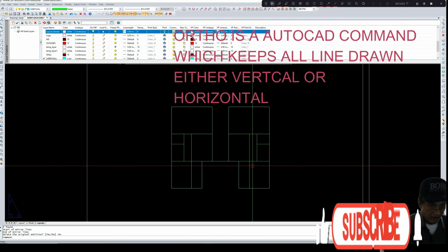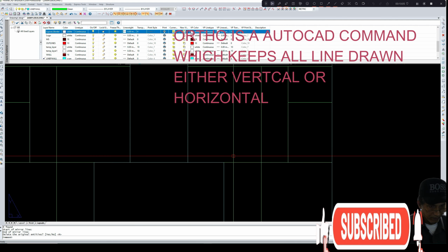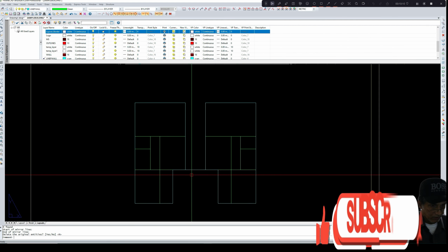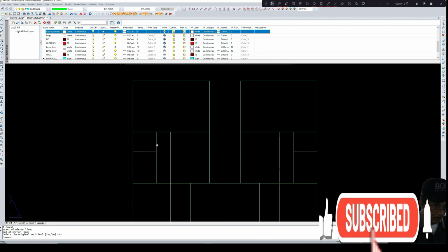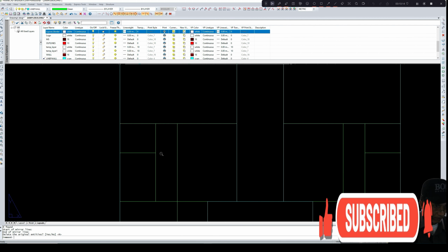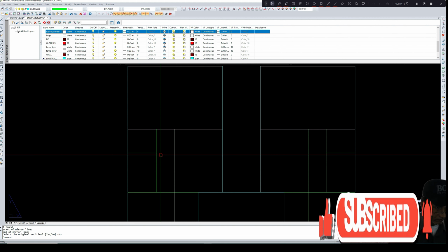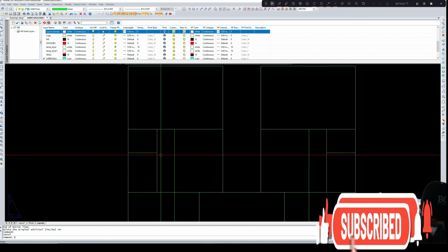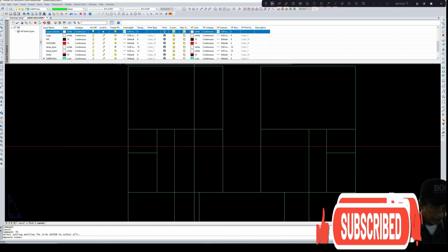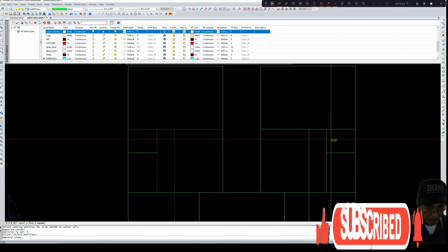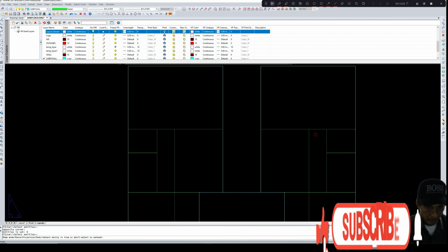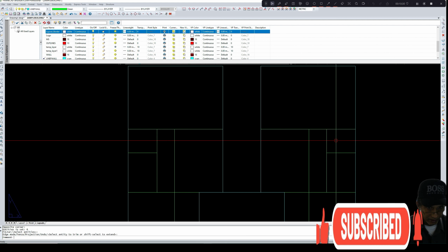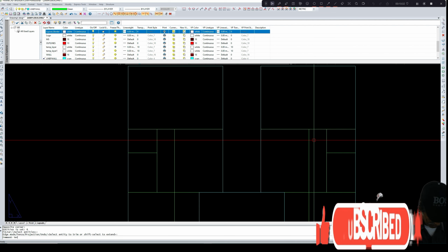So we've got the lines for the internal wall. Now we do not have walls at certain places, so we have to use the trimming command. So TR, then select those lines and then enter, then select the part to be trimmed.